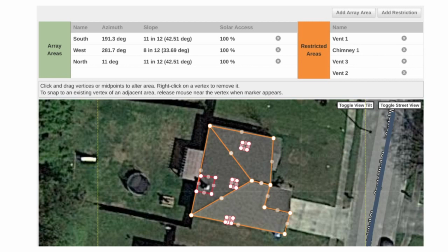There are exceptions. An ugly solar array does not add as much value to a home as a pretty solar array. So if the array's look is significantly improved by putting a solar panel a little bit closer to that chimney, it may be acceptable so long as the client understands the design decision. In any event, clearance space around the chimney is more important than clearance space around a plumbing vent, and staying clear of these obstacles removes the need for nuance.